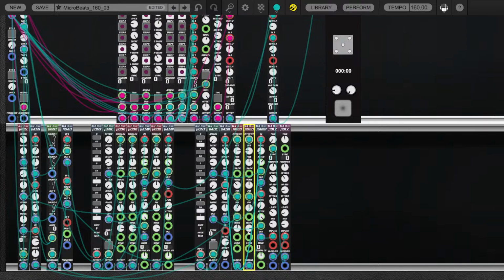And the modulator oscillator is also detuned quite a fair bit to get this dissonant tone. And again, the output is shaped by an amplifier and an AD envelope before finally being fed into the phase modulation input of the carrier oscillator, which is also shaped by an amplifier and an AD envelope. And then we use a delay with a very short delay time and a much attenuated sine wave from our sine LFO here at the beginning. And this is really almost 0 modulation here to get this makeshift chorus.